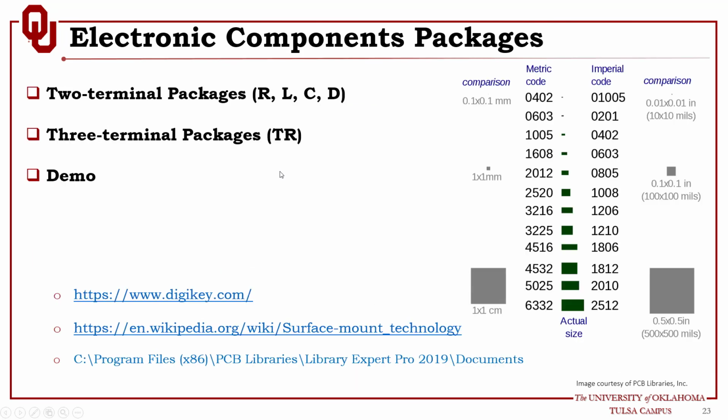Now, when it comes to the packages of the component, the package size of the component itself depends upon several parameters, such as how much power the component can handle in case of 2, 3, 4, and 5 terminal packages, resistors, capacitors, transistors, and so on, or the functionality provided by the component, such as the number of input-output pins of the microcontroller. So if you have a microcontroller with 28 pins, maybe the IOs on that microcontroller are around 22 input-output pins. If you need more IOs, like I need 50 input-output pins, you might need to go into a microcontroller that has at least 64 pins, and so on. So there is no specific rule to specify the package size of the component and the number of pins on the component, other than the functionality and also how much power the component can handle.